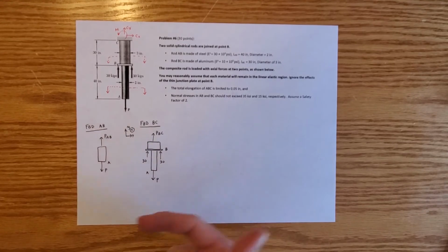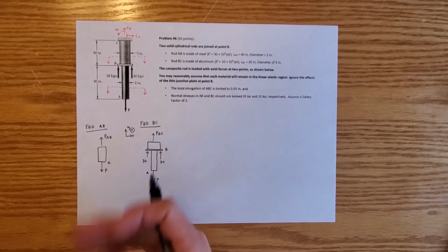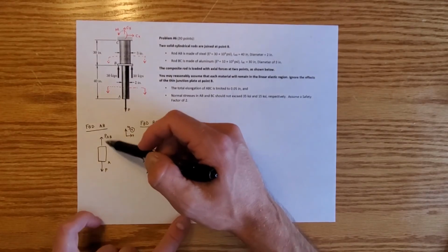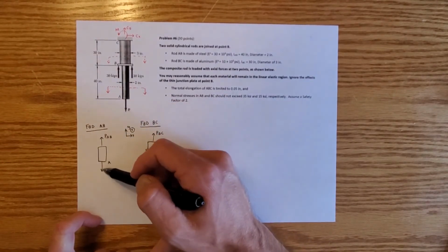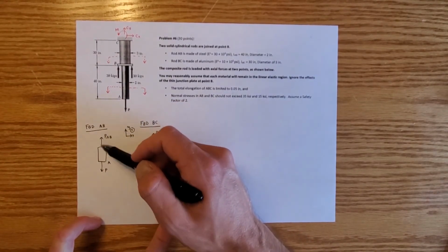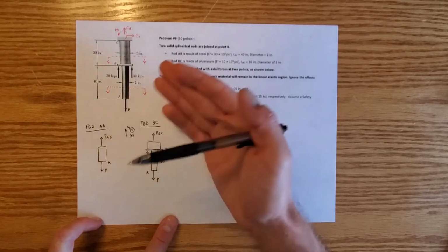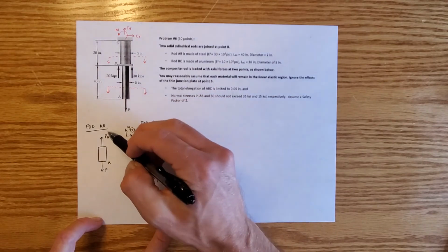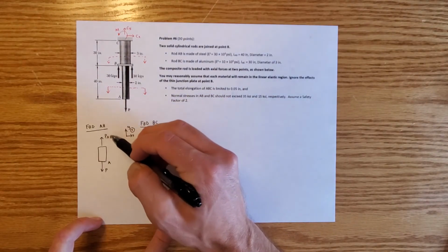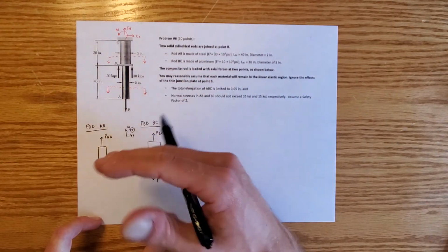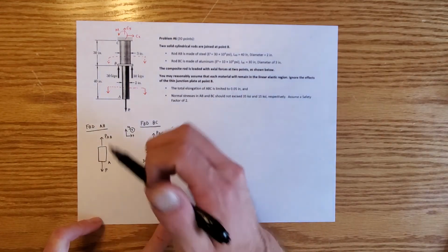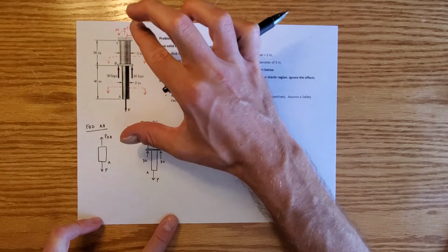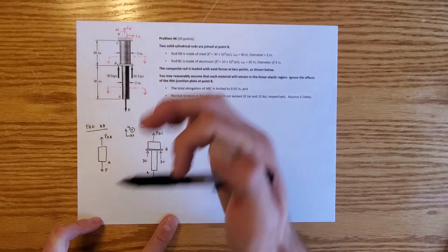Now that I've got the free body diagrams of AB and BC, we can look a little bit closer and see what we would do next. If we look at rod AB, we look down, we see the cut P, and then we see PAB, the normal force, going out. The way that rod problems are different from internal forces problems is that we're only looking at the normal forces inside the rods. We're going to disregard the shear and the internal bending moment. We're mostly focusing on determining whether the rod is stretching, compressing, or things like that.